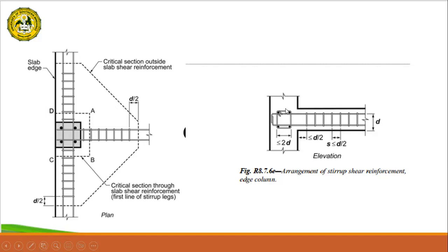beam joint, no? So nakikita nyo dito, ito yung stirrup ng beam na yan. Then ito naman yung stirrups ng beam in this direction, no? So as you can see, yung development length ng top bars ng beam is extended to the support, depending on the calculated development length, plus it is bent with a hook. So ganun din sa bottom bars, it is also bent with a 90-degree hook. Then yung ating stirrup here is less than or equal to 2 times the effective depth.